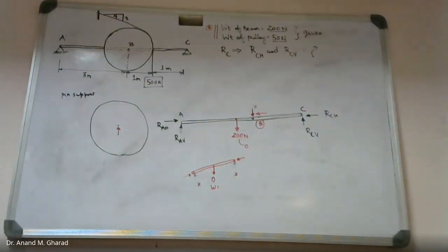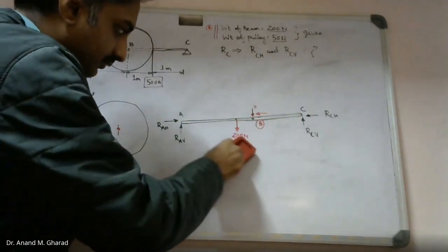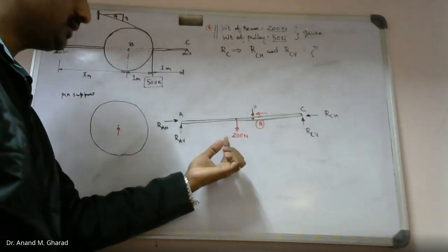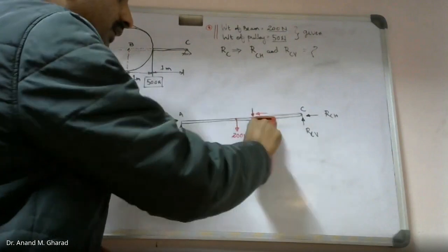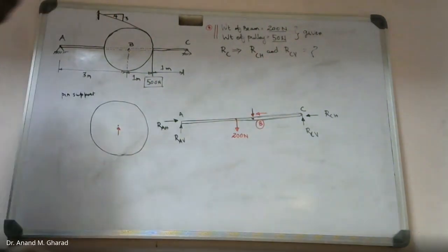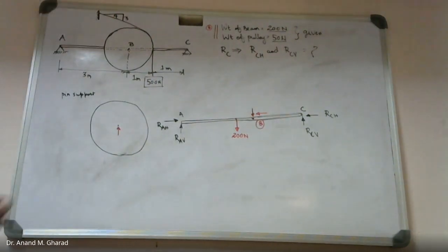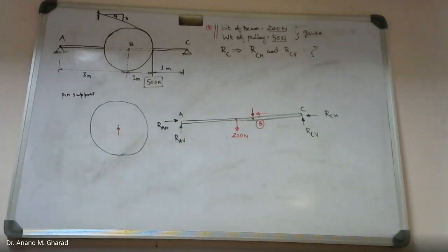Okay. So over here in this numerical, you are supposed to take care, since the magnitude of the self weight is given. Therefore, we will have to consider the reaction forces. Those will be developed in both the directions, that is in the horizontal and vertical direction at point B, because at point B, two rigid bodies are connected with the help of this smooth pin. Got it? Is this okay?